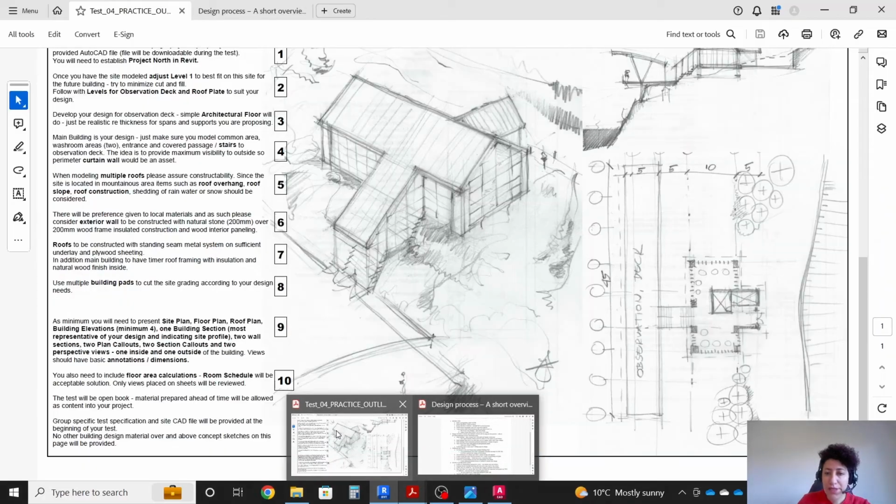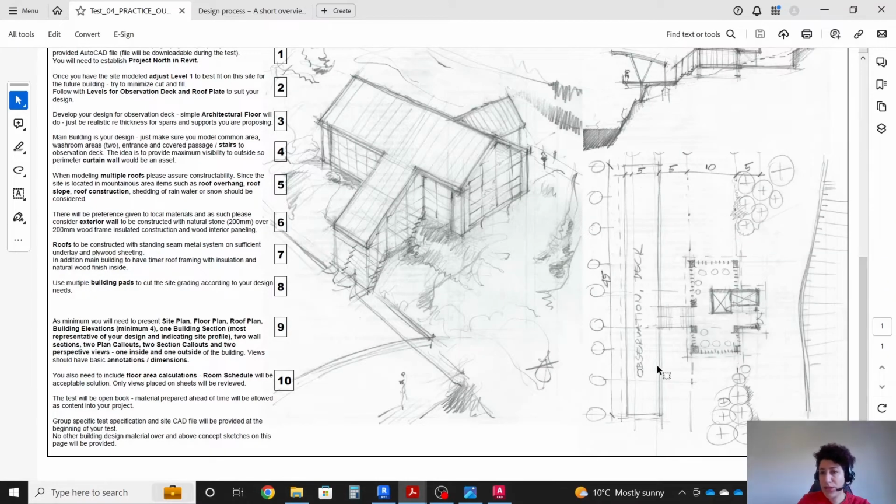So, this sketch is actually 90 degrees rotated the other way, but that's okay. So it seems that for the main area, we have a span of 10 meters at the middle and a span of 10 meters on this end too. So I want to go with spans of 5, 5, 5, 5, then 10, and then 5, 5, 5 meters. So 5, 5, 5, 5, 10, 5, 5, 5, right?